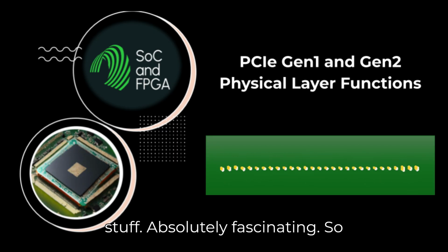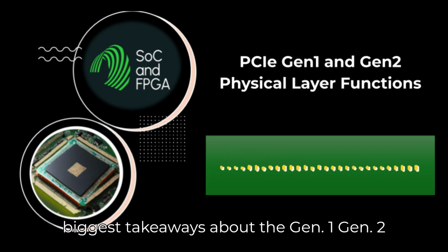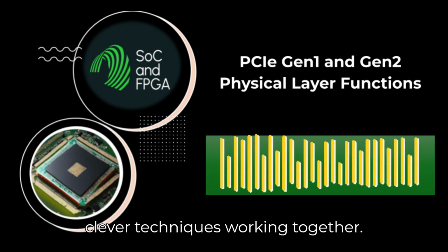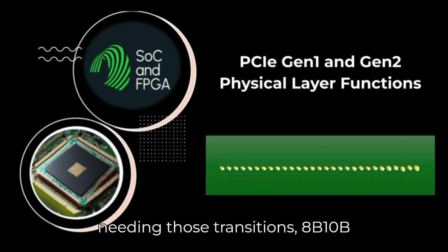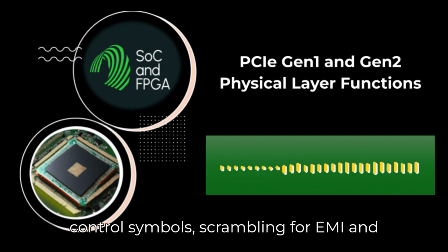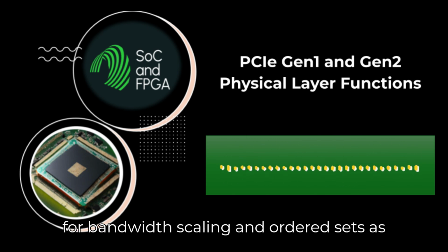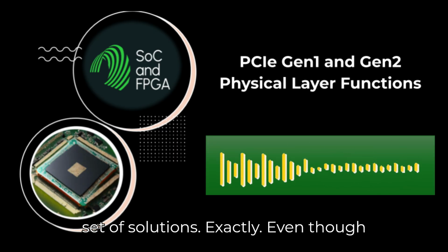Sophisticated stuff. Absolutely fascinating. So wrapping up this deep dive, what are the biggest takeaways about the Gen 1, Gen 2 PHY? I think it's the combination of clever techniques working together: SerDes for the speed conversion, CDR needing those transitions, 8B10B providing transitions, DC balance and control symbols, scrambling for EMI and randomness, multi-lane striping with deskew for bandwidth scaling, and ordered sets as the PHY's own control channel. A layered set of solutions.